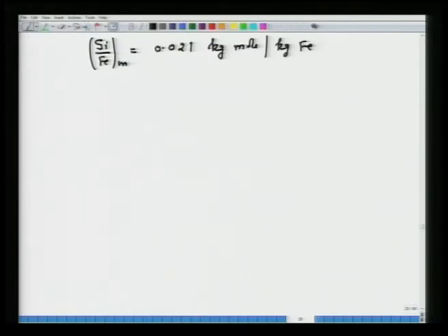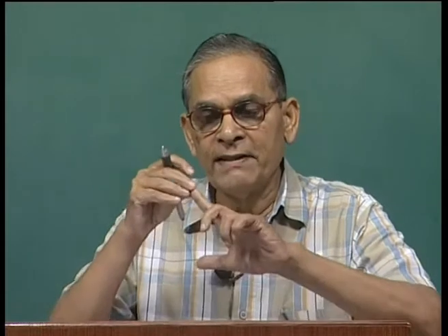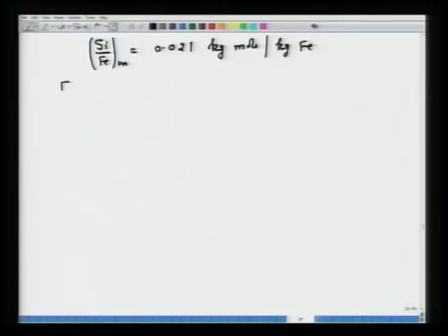So, what do we have to do now? On the heat demand side, in case B we added the enthalpy for carbon. Now, in case C we have to add the enthalpy required for silicon, because it will be raised from 298 to 1800 Kelvin, and the enthalpy required to raise the temperature of manganese from 298 to 1800 Kelvin. So, we need the enthalpy of manganese, and we need the enthalpy of silicon.